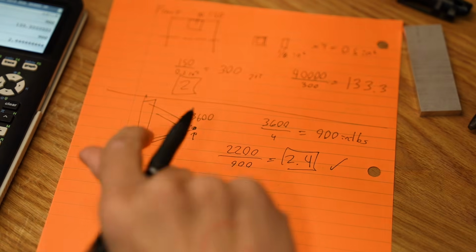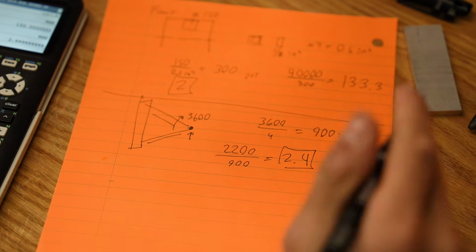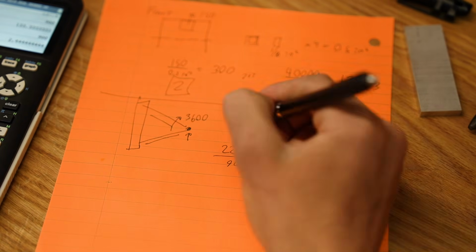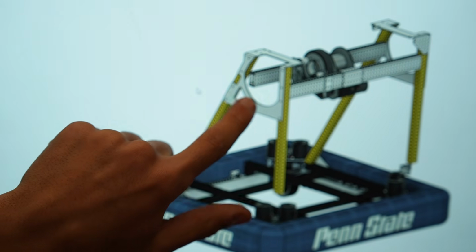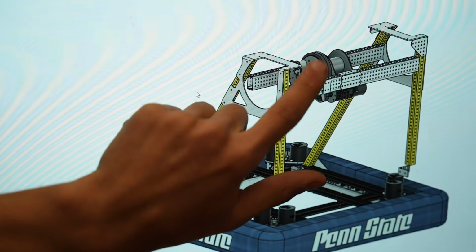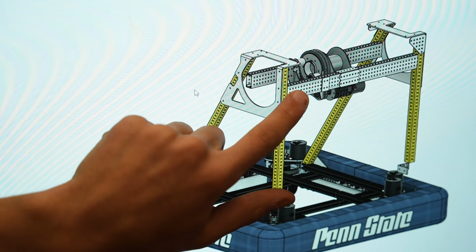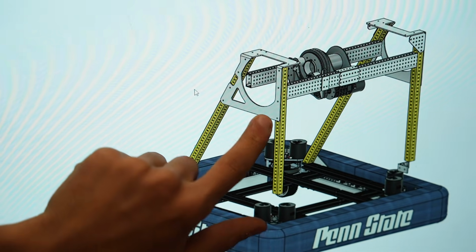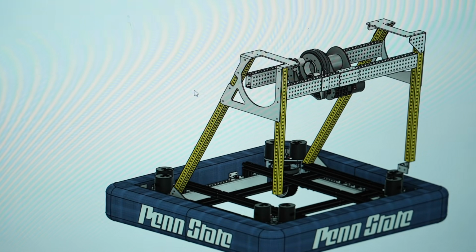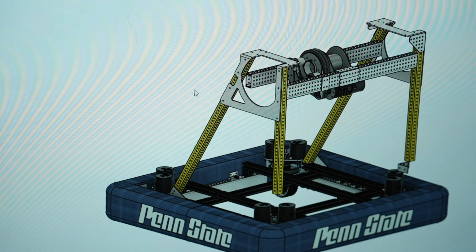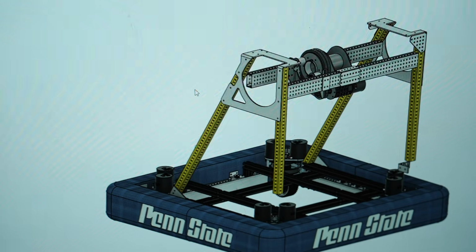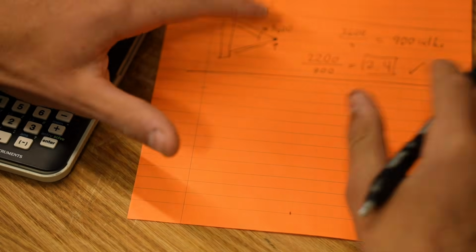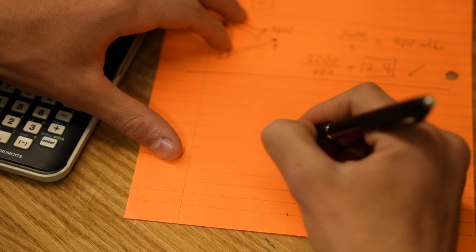Where this will get you is if you don't gusset your 1x1 well enough to support that 3,600 inch-pounds of load. As you can see in our CAD here, we transfer that load from our torque assembly through 1x2 tubing into our 1x1s through pretty large gusset plates. These are likely overbuilt, but you do need some ability to transfer those forces. The final part of the superstructure we're going to look at is how we're supporting the torque assembly.